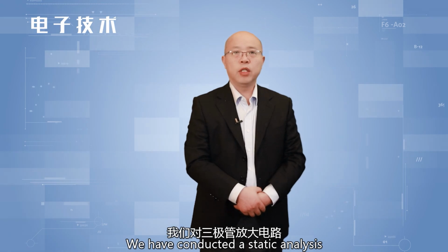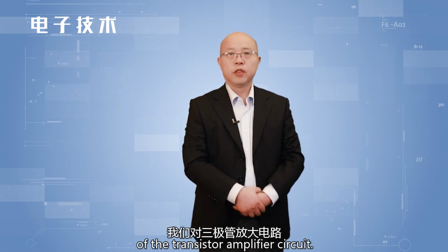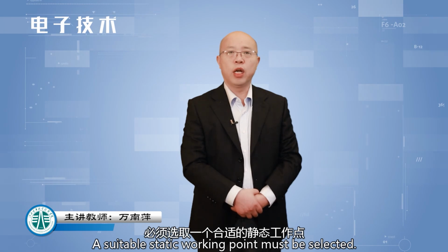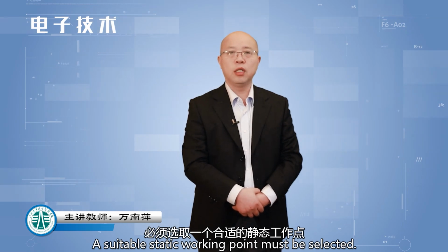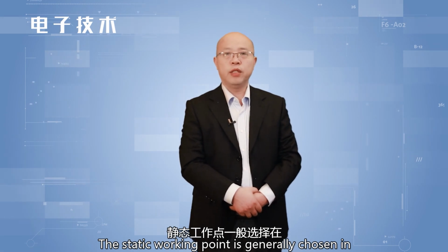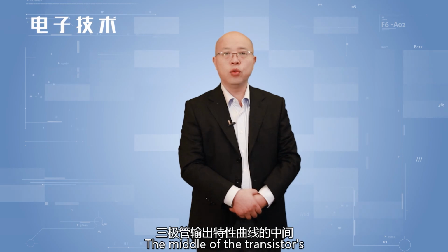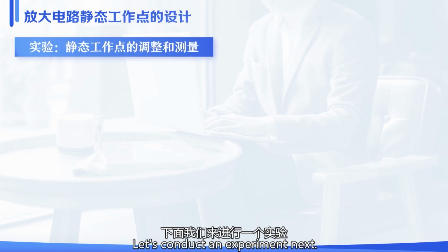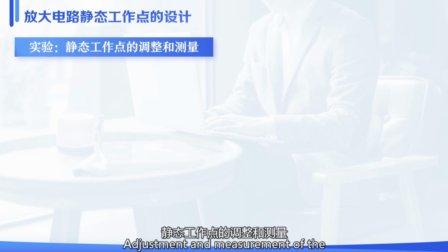We have conducted a static analysis of the transistor amplifier circuit. For the amplifier circuit, a suitable static working point must be selected. The static working point is generally chosen in the middle of the transistor's output characteristic curve. Let's conduct an experiment next: adjustment and measurement of the static working point.